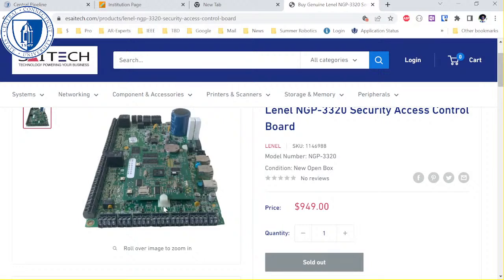These things. So there's lots of lettering on the box. These little square things, they're capacitors and resistors. They're surface mount capacitors and resistors. This thing here. Most of the white stuff is lettering, but it's circling. All of these things around the outside, they're RS485 buses, so they're serial buses, and they need some protection and drivers and stuff.